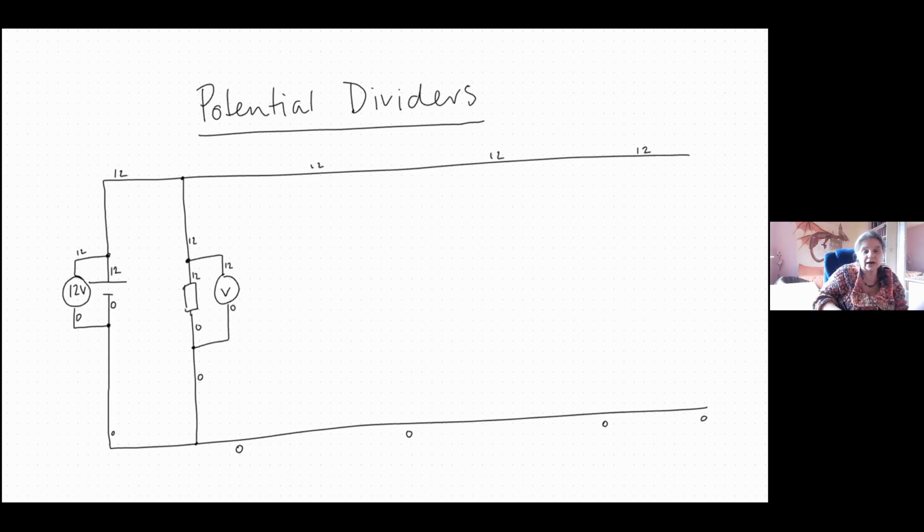What is that voltmeter going to be reading? Well, 12 volts, yeah, absolutely. It's 12 minus nothing, it's 12. Well done. Good. Okay, so now I'm going to remove it because adding in voltmeters, they don't take part in the circuit. They don't count as part of the circuit unless they've got a low resistance, in which case you can deal with them as if they were a resistor.